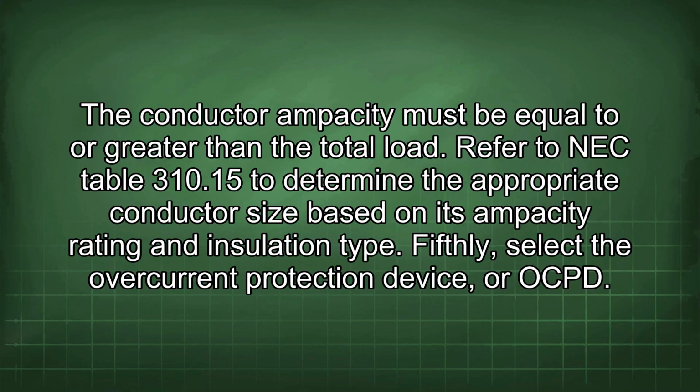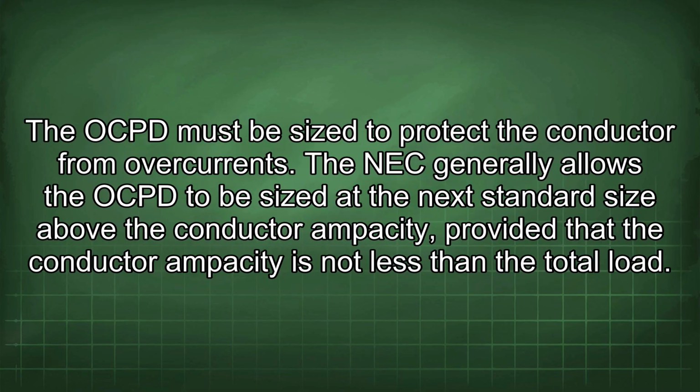Fifthly, select the overcurrent protection device, or OCPD. The OCPD must be sized to protect the conductor from overcurrents. The NEC generally allows the OCPD to be sized at the next standard size above the conductor ampacity, provided that the conductor ampacity is not less than the total load.